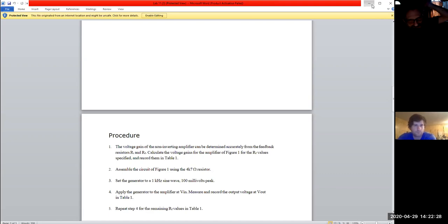So it got overloaded. Now it doesn't kick out anymore. Well, the funniest thing is it usually will work, but they use a Zener as a reference. What it looks for is like a safety check. It compares the 5 volts to the 5 volts. So the power supply is generating 5 volts, but it has current, right? So that's a nice kick to it. And then you use a Zener as a reference to compare: is my 5 volts really 5 volts?